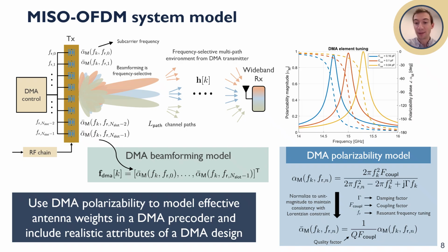We see that the resonant frequency tuning there is what is actually tuned by the varactor diode. So if we tune the CVAR value, that will tune the resonant frequency, which is also what we see in the plot there.